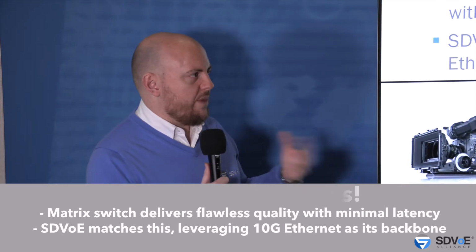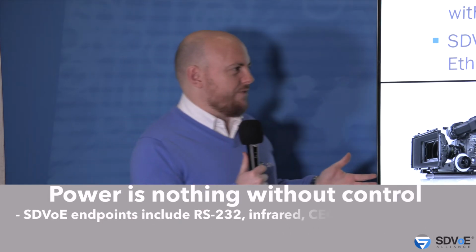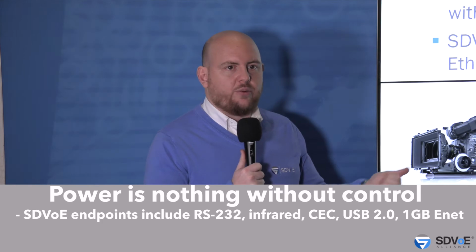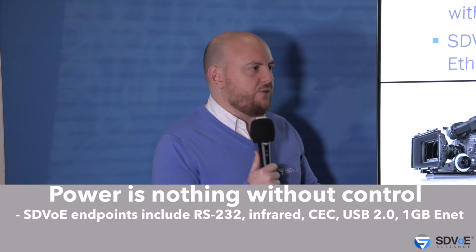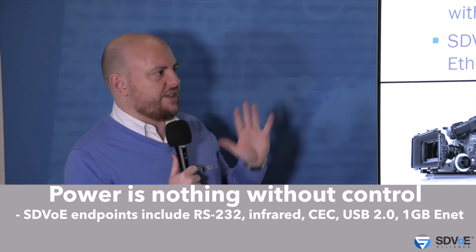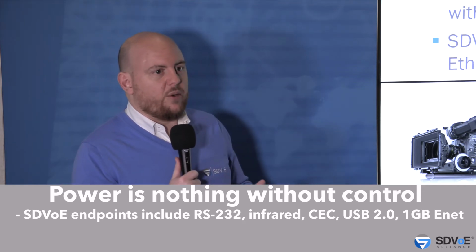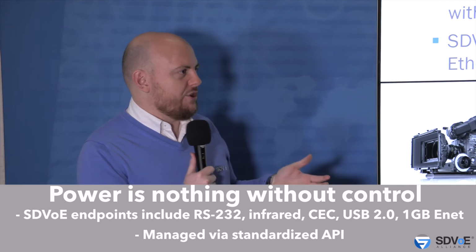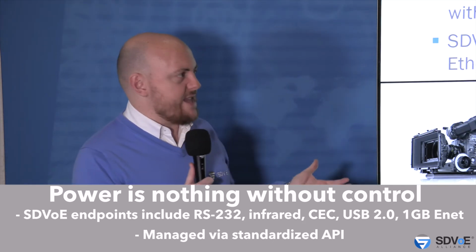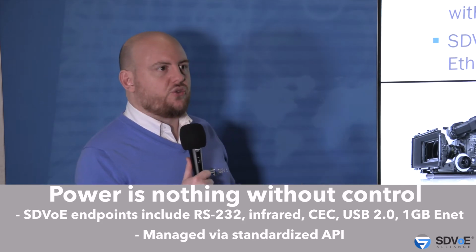In Pro AV, of course, the matrix switch has adapted to a lot of extra features that don't strictly have to do with moving video around, right? These are the control ports out on your receiver, you know, to have an RS-232 connection to the TV to turn it on and off. CEC, infrared, all of these control signals have been built into the high-end matrix switches to help extend that control network, right? Because honestly, who cares how good your video quality is if you can't turn the TV on?